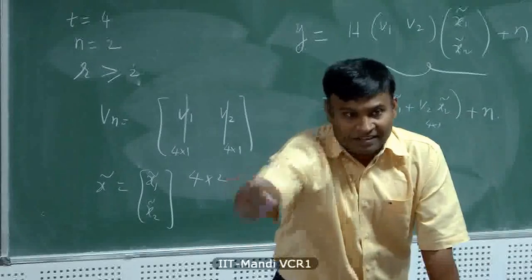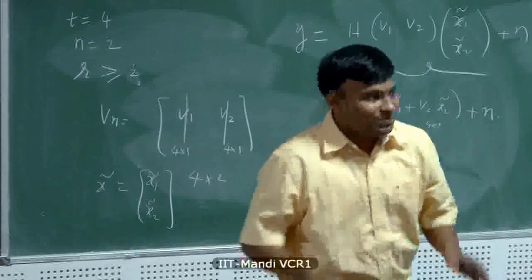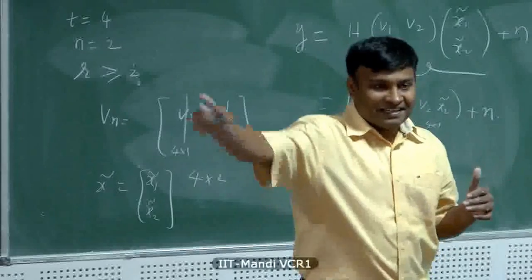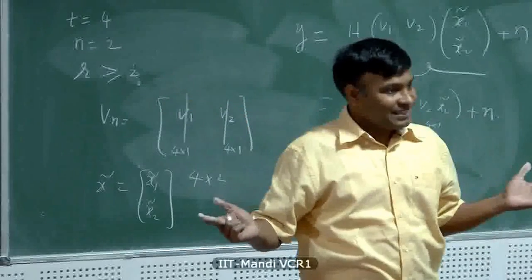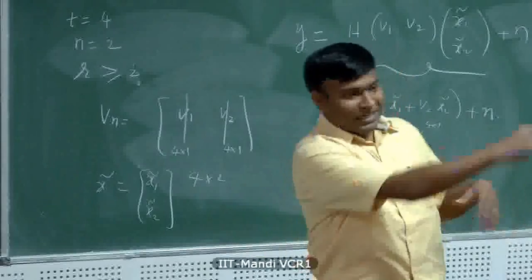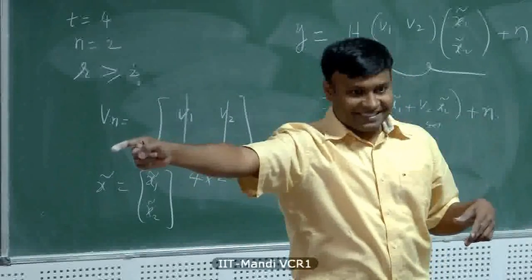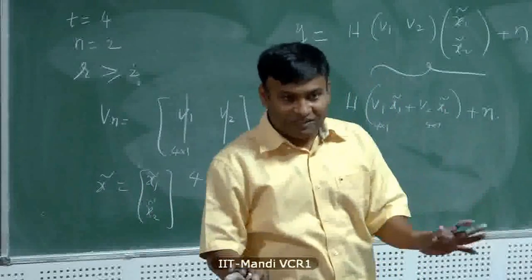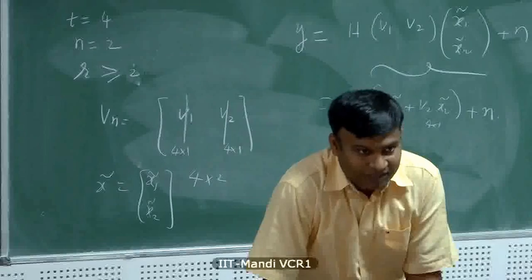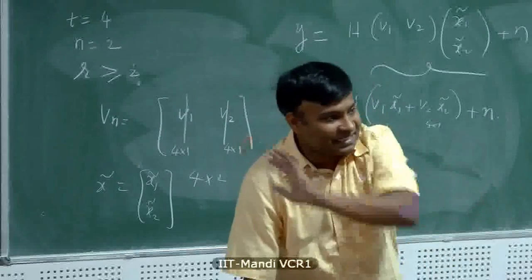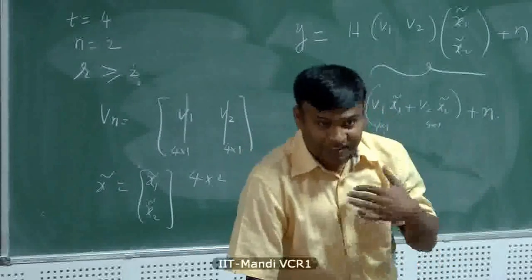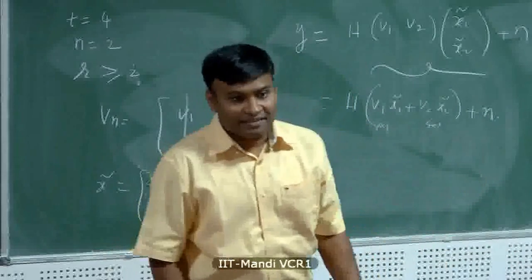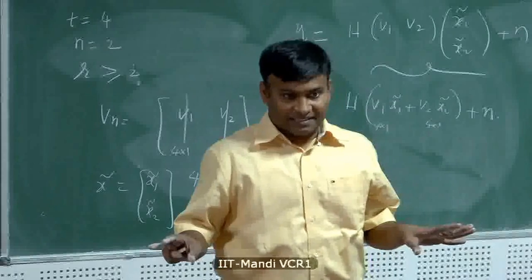Let's say you put a third antenna in that corner and a fourth antenna in that corner. Where should I put my beam? In the limiting case, as the number of antennas increases arbitrarily, the array gain vanishes. Then what you should do is not put a beam, but radiate uniformly in all directions. So there is no array gain. Instead of looking at this mathematically, that's probably the best way of explaining it. You can show even mathematically that as the number of receive antennas increases arbitrarily, and the transmitter is sending a single beam, a single stream, you lose your array gain completely.